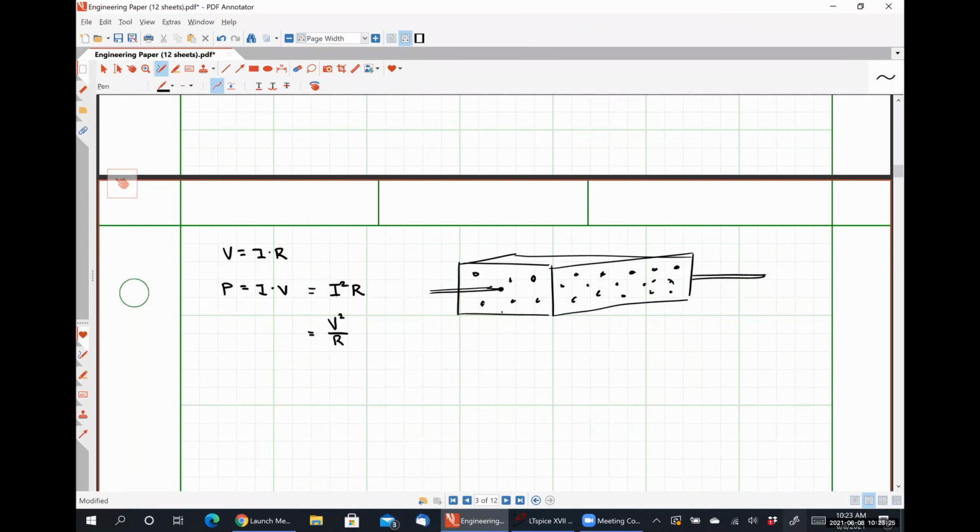And so what that means is that, let's say an electron is trying to pass through this bar, it bounces off this atom and has to turn around, and it follows a very weird, jagged, bouncing around path all the way through until it reaches the opposite end of the bar. Well, every time any of these electrons hit one of these atoms within the structure of the resistor, it generates heat, okay? And so that generation of heat is how the resistor absorbs energy, okay?